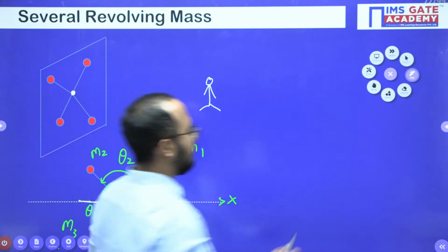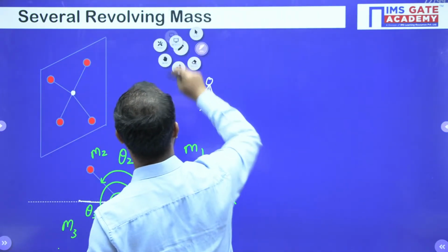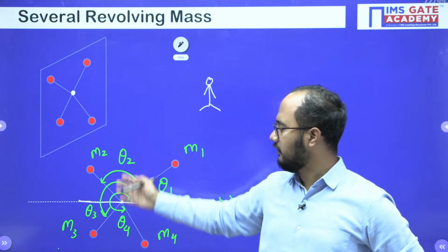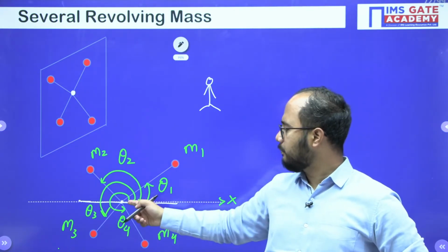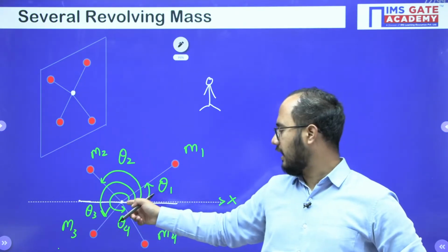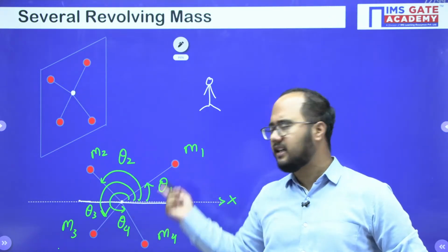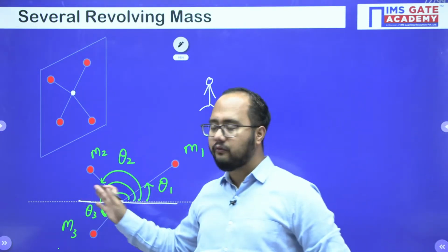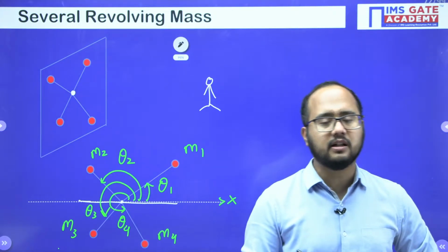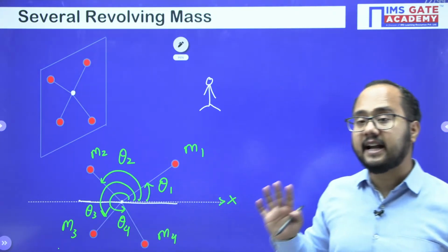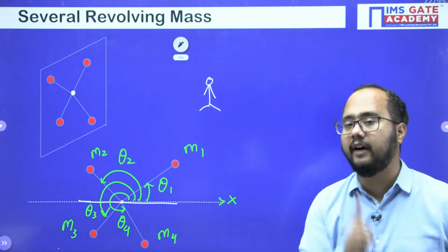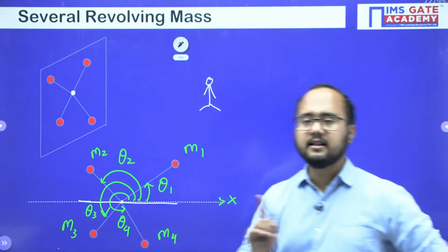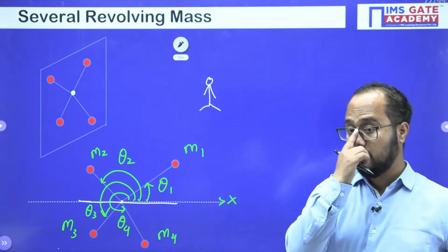Here itself I will mention, so that the diagram will also be clear and you can easily mention everything. Now this is the case in which different masses are there that I need to balance. As all the disturbing masses are connected at a point, I can easily attach one mass and balance the whole system. But if they are placed at different locations, I cannot balance the whole system with a single mass. In this case I can, why? Because all the disturbing masses are connected at a single point. Is this point clear?